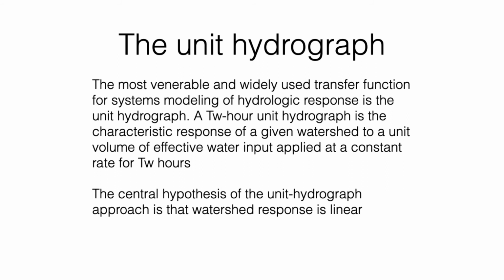The last rainfall runoff method that we are going to cover in this lesson is the unit hydrograph method. A unit hydrograph is a hydrograph that corresponds to a unitary effective rainfall, normally unitary in volume, a total volume of rainfall of 1 unit, but in some cases it may also refer to unitary intensity. And the unit volume corresponds to this unitary effective rainfall, but that lasts for a given time.